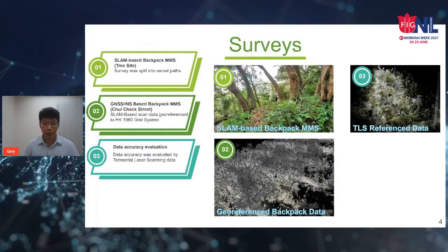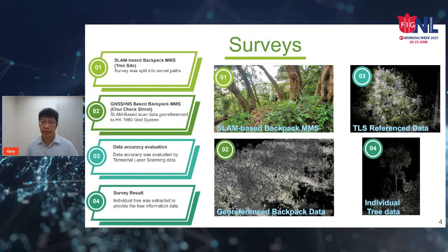In order to evaluate the accuracy of the backpack MMS data, reference point cloud was surveyed using terrestrial laser scanning (TLS), with the control points established by conventional traversing and leveling. The evaluated results will be discussed further. Lastly, we extracted the individual tree scans to collect the tree information data.